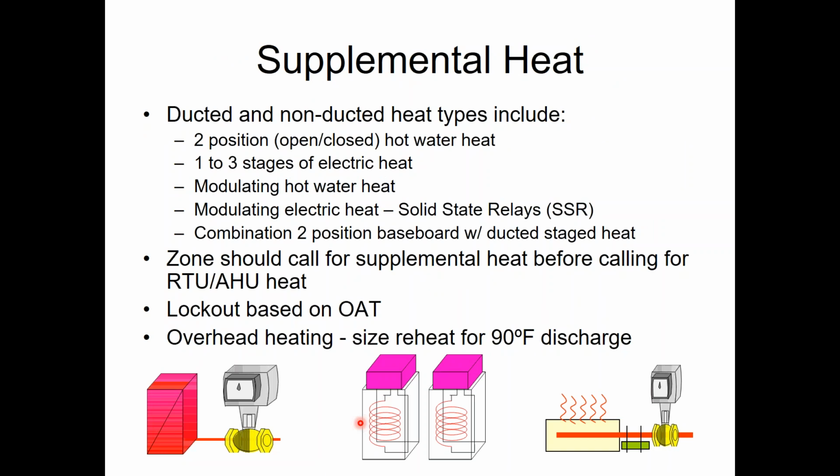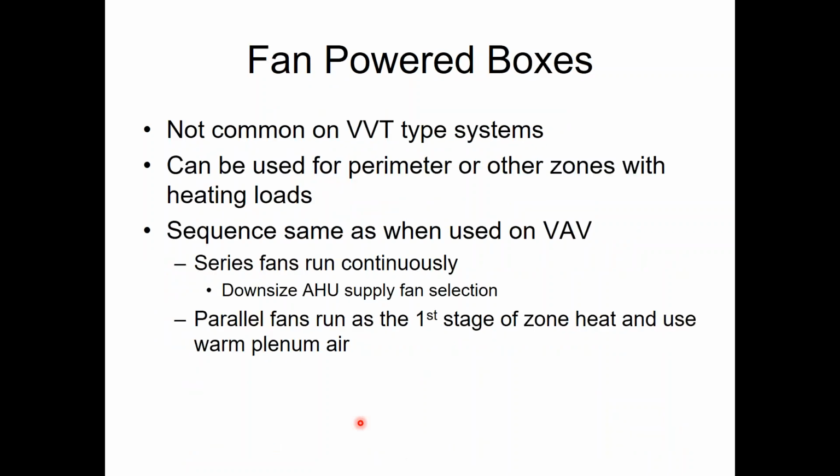Any kind of supplemental heat you could put on a VAV system, you can also put on VVT. So duct heaters, baseboard heaters, electric, hydronic, any of those things you can do. It all works exactly the same in that regard. And we'll talk more about that for you guys that are joining us in 2 weeks on the air handlers. Same thing with fan power boxes. I'll talk to you about those in a couple weeks when we do the air terminals, VAV air terminals.